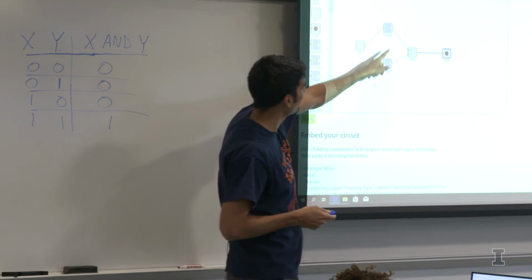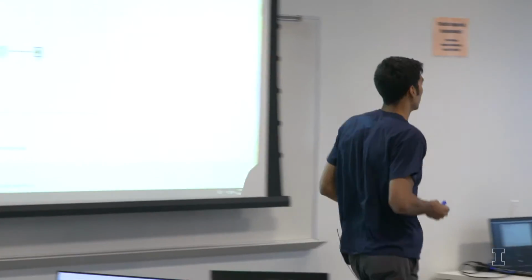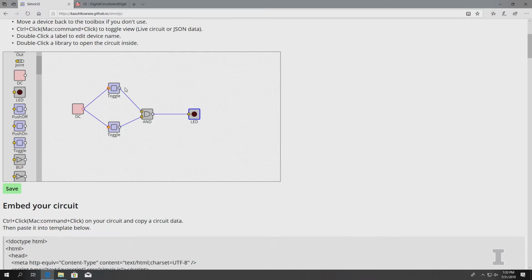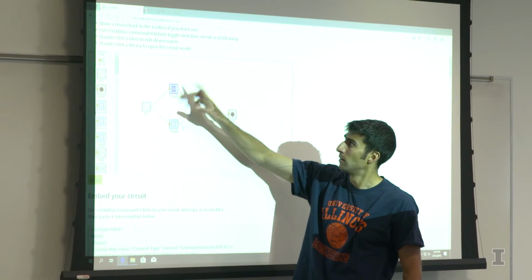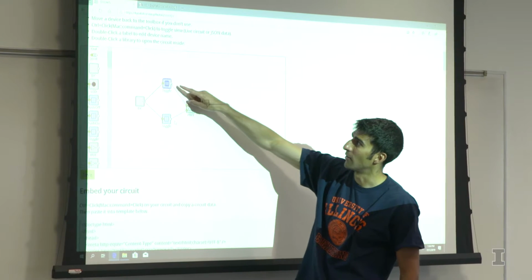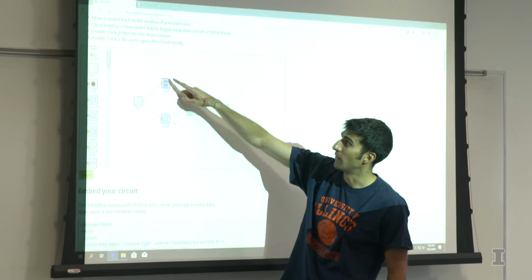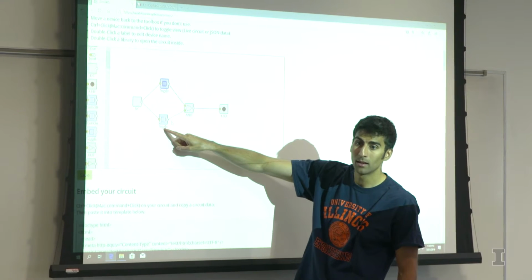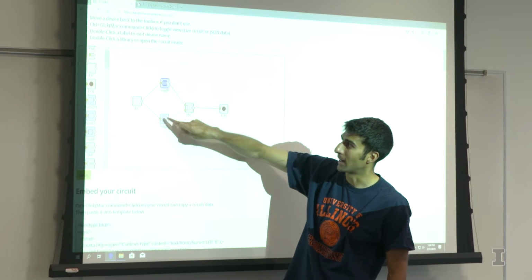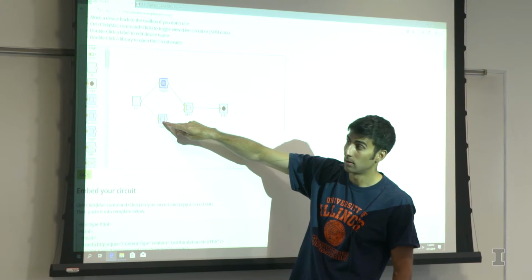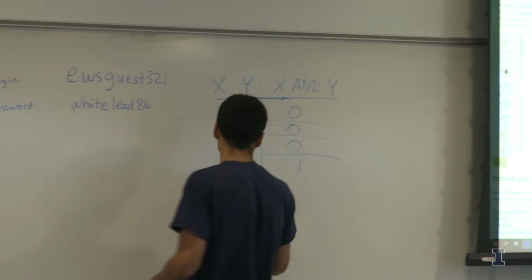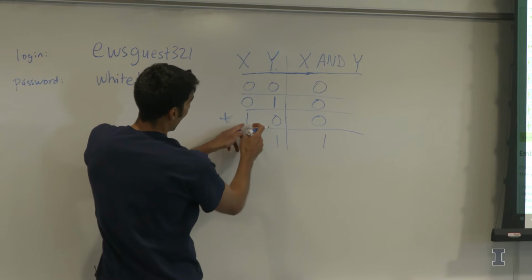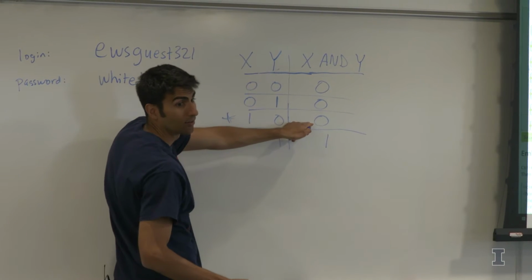So you're pressing these. Let me. So I click the toggle. So right now, when you click it once, now it's pressed. I don't know if you can make it out on the screen, but it's actually gray inside. I pressed it and nothing, it was still, I'm assuming, off. Right. So the way to interpret this now, this is gray inside, and that's not gray. So if we call this toggle X and we call that toggle Y, that would be like this toggle X is 1 and toggle Y is 0. And the output is the LED. And that was off. So that would correspond to, right now we're looking at this row right here. X is pressed, Y is not pressed, and the LED is off.